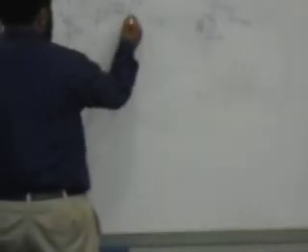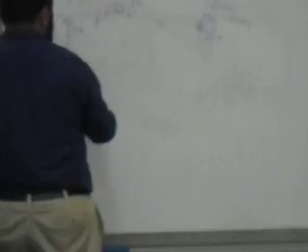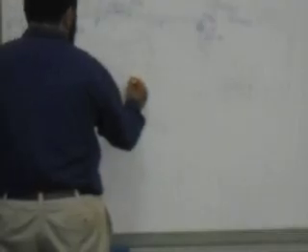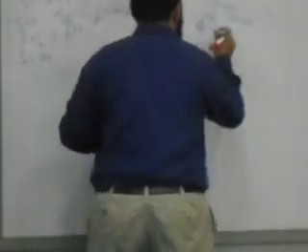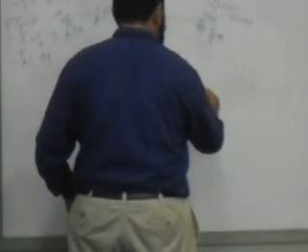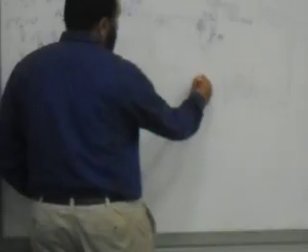I have the 3 going down like this. Is there anything until receiving the 5? No, so this is negative 3 constant, then a 5 going down, this will be negative 8. That's an 8, negative 8. Then negative 8. Here it goes to the support, it receives the 8, it closes to 0.